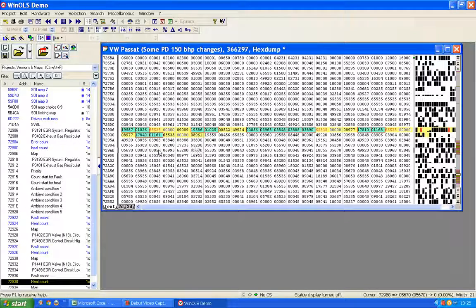Or another alternative is, of course, I do this, I go and check the car is absolutely perfect, there are no errors displayed, and then in 2 months' time or 3 months' time, I've suddenly got errors. And then when I scan the car, I find I've got EGR errors, even though I've got all these turned off. You think, well, what on earth's going on there?